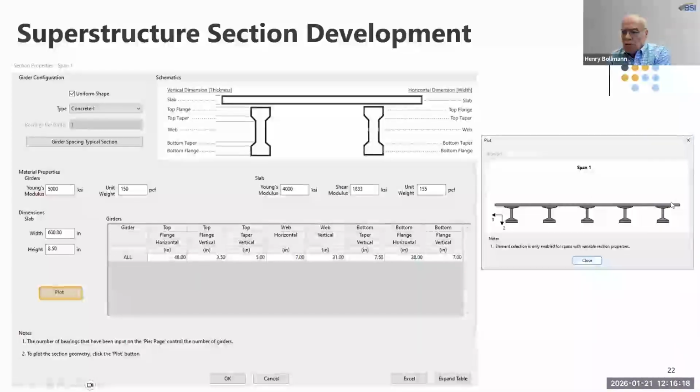And this gives you a warm, fuzzy feeling here that everything looks fine. You recognize these girders. They look exactly like they should. You can just eyeball those. Notice the local 2-axis is vertical, which means that the strong axis for bending for the deck slabs that we're talking about is about this 2-axis. That'll come into play when we talk about the continuity element.